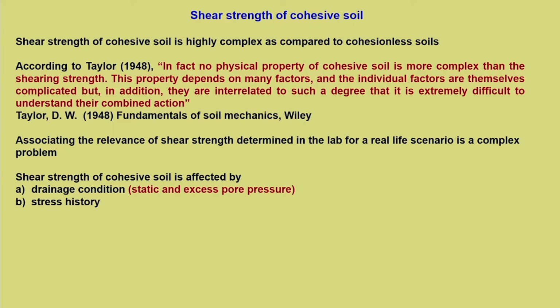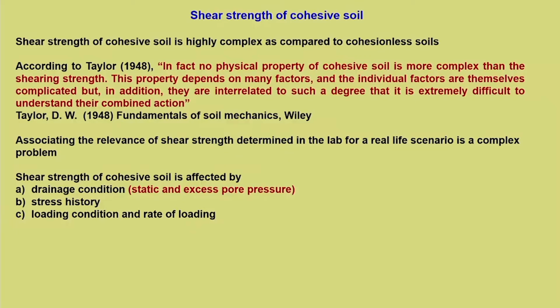The second is stress history. Now, if you consider the shear strength of undisturbed soils, then stress history becomes its initial state, like what this soil has been subjected to in the past. I hope we all agree to the fact that soil carries certain memory along with it, which gets erased and rewritten every time we load it. So, this aspect also will become clear as we proceed. So, stress history becomes very important.